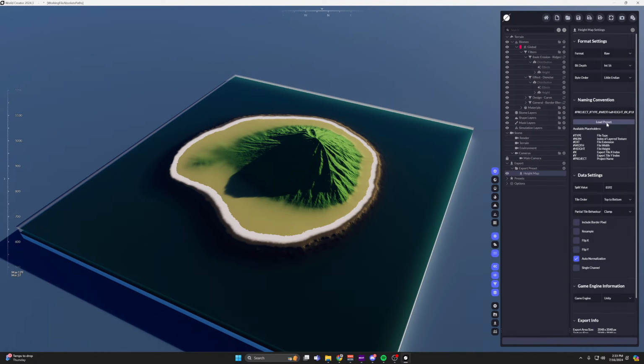The only caveat to Twinmotion for the terrain aspect is you can't import the terrain, like if you had a material for the terrain. So what you would have to do is just import a model. So what we're going to do is in here, we're going to model the terrain, export an FBX or OBJ of the terrain with its textures applied to it, all combined, and then import that into Twinmotion.